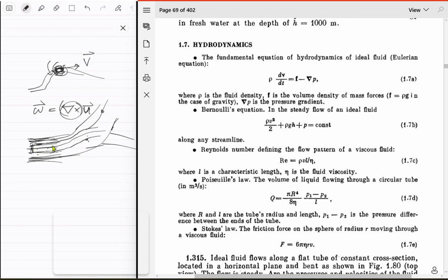well, should they have the same velocity? I think they should, right? Because otherwise, how can you do this? I mean, of course they will have the same velocity, right? I have never seen a question where the velocities are different. And that's why I'm assuming. And okay, if their velocities are different, then that means there's a gradient, which means there are viscous forces. So that explains why we can assume the velocity will be the same everywhere.